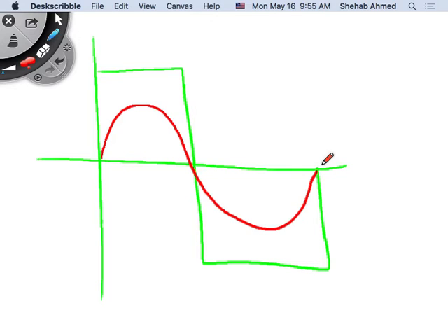Because we said we were going to add these up to create this one. So how do I add more to create this? I add something at, let's say, 50 hertz, fundamental frequency, omega naught, right? And let's say I'll add a third harmonic, 3 omega naught. Add these two together, fine. I will get something that rises a little bit faster than both of them, but still not as sharp as the square wave rise. Right? So, okay, maybe I need to add a 5 omega naught.